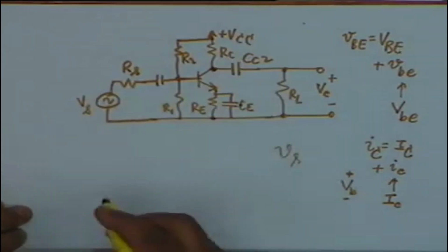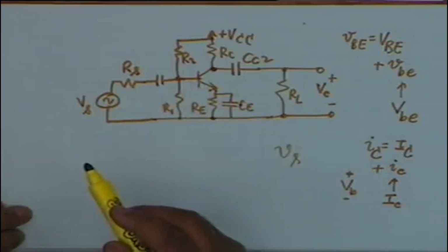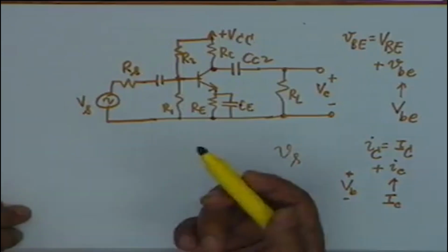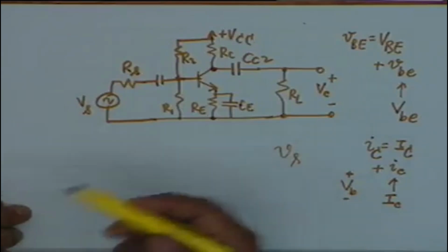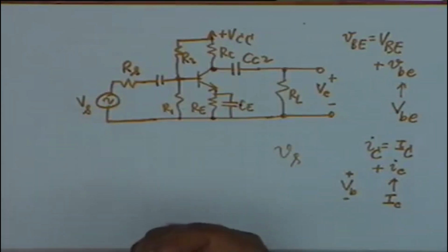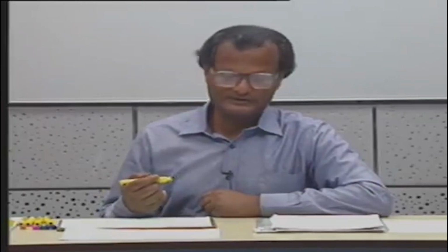We shall follow this discipline throughout. For example, the AC base current shall now be denoted by capital I subscript small b. That means the root mean squared value of the signal current. And as I have repeatedly told you, we can divorce signal quantities from DC quantities, and therefore we can analyze by means of the small signal model of the transistor.